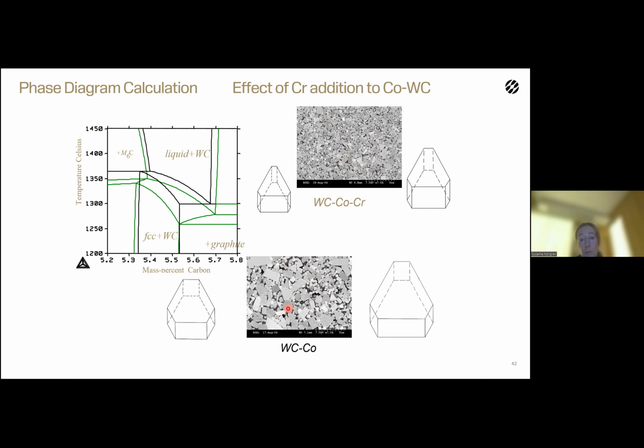And then I've also tried to draw the different shapes of the crystal here, exaggerated, but to scale, so you can also see how the addition of chromium and the addition of carbon, higher carbon to the right, is affecting the grain shape and the distribution or the fraction of basal to prismatic planes in the crystal.